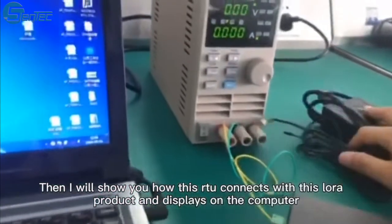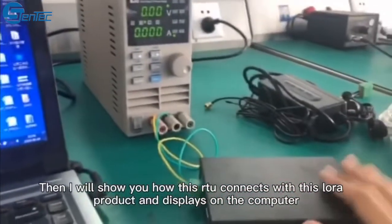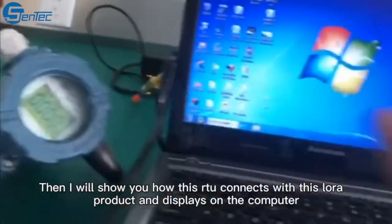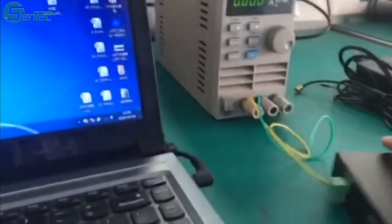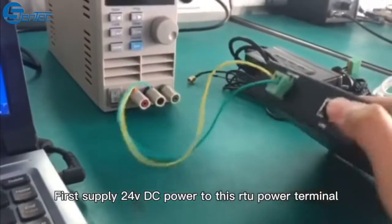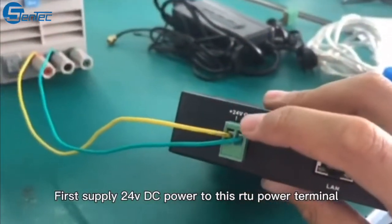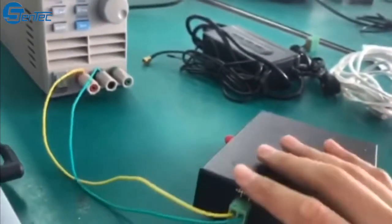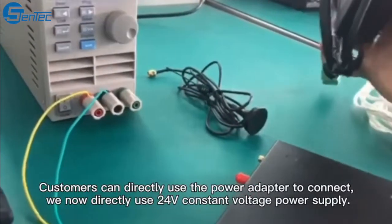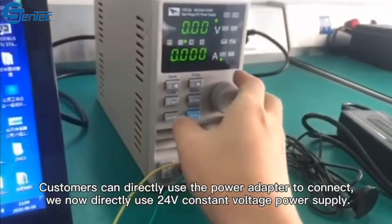Then I will show you how this RTU connects with this LoRa product and displays on the computer. First, apply 24 volts DC power to this RTU power terminal. Customers can directly use the power adapter to connect. We now directly use a 24 volts constant voltage power supply.